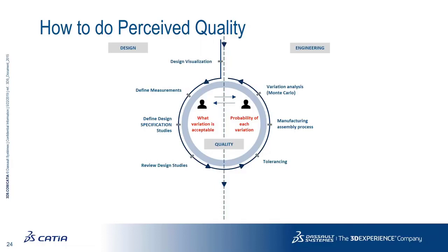They do the tolerancing, and as you know, in the manufacturing processes, every part looks a bit different to the one before, or it is not 100% exactly the same as before. So now there comes simulation data into the topic. They can simulate the manufacturing process and the building process of the single parts, and they can predict which variation they can meet in the end.